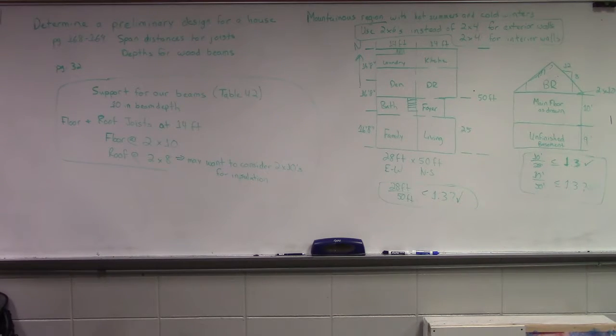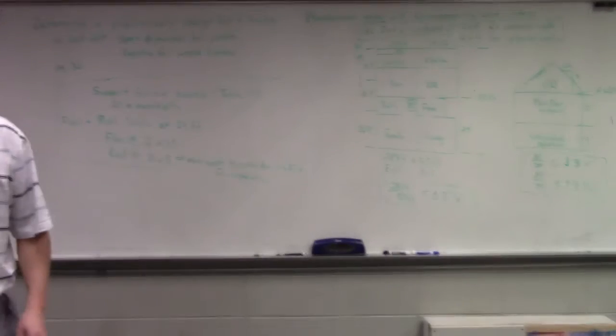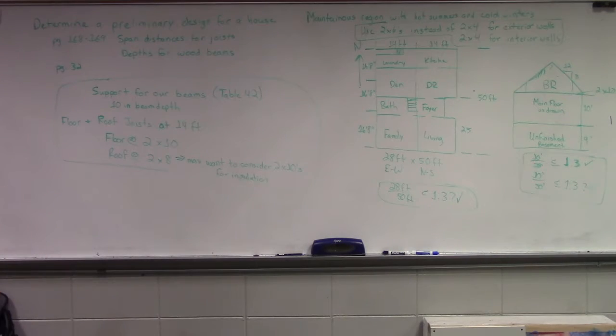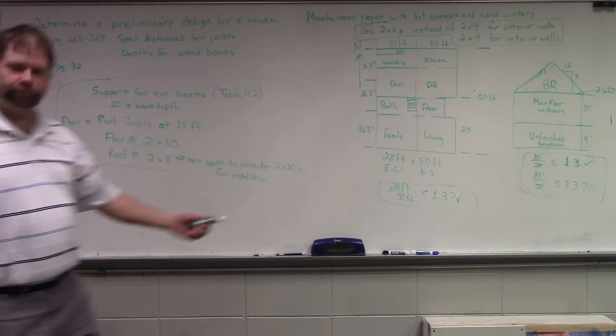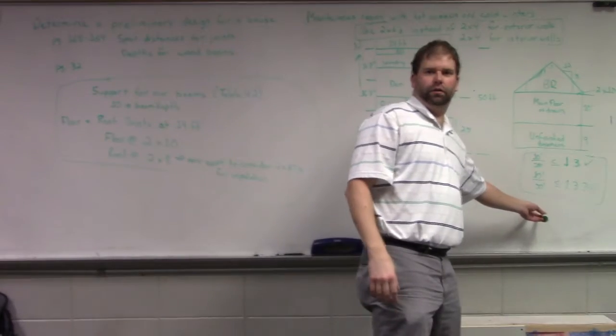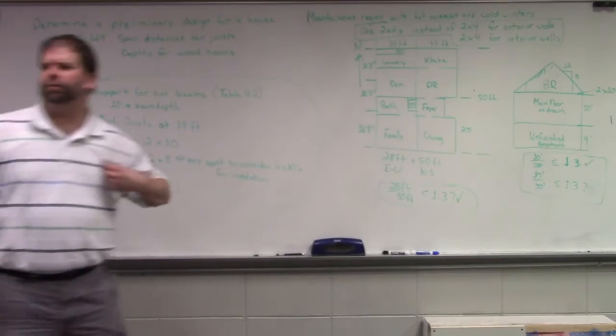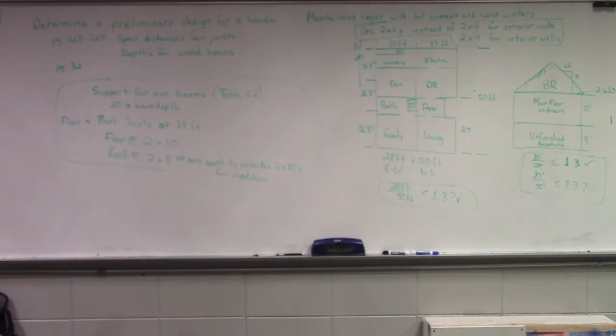See, I'm still stuck on the bedroom. So a shear wall, you've got the 50-foot wall on the backside of the house, and it exceeds 1 to 3? So that doesn't make it stronger? For 10 feet height, it's 50 feet long, wouldn't that be stronger than if it's 10 feet high and 30 feet long? It's not necessarily that we're worried about it being stronger. We're worried about how it's going to pick up that load and effectively distribute it. That's what we're concerned about.